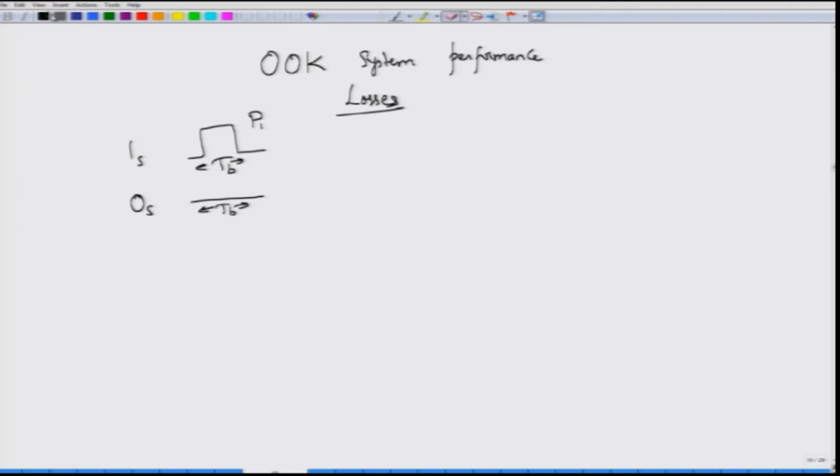Okay. The transmitter side system consists of a laser which is producing your continuous waveform. So, you have a laser here which has a carrier frequency of omega s. This can be pulse shaped using one of the pulse shaping components that we discussed, such as a Mach Zehnder modulator, and then you have an amplitude modulator that you can use in order to turn on and turn off the pulse shaping circuit.